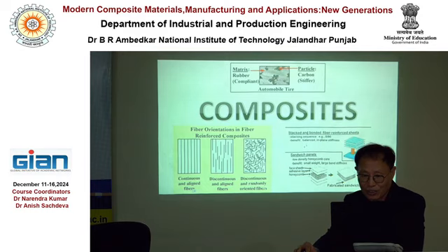This is the case, the stacking and bonding of each ply. So to satisfy some designated purpose of a structure, we can intentionally make its stacking sequence different. Okay? It can be calculated for having the desired stiffness in spatial directions. As a result, the benefit is it's well balanced, and the in-plane stiffness can be easily obtained as desired.